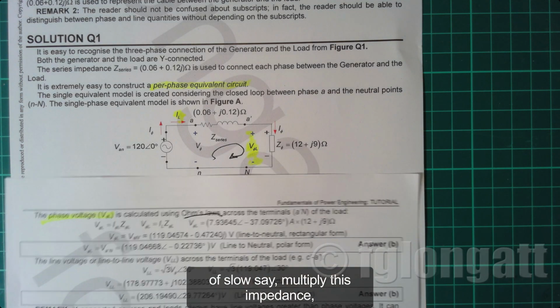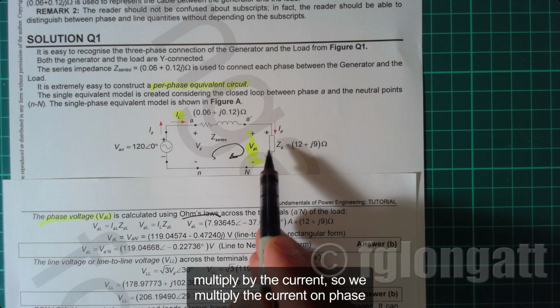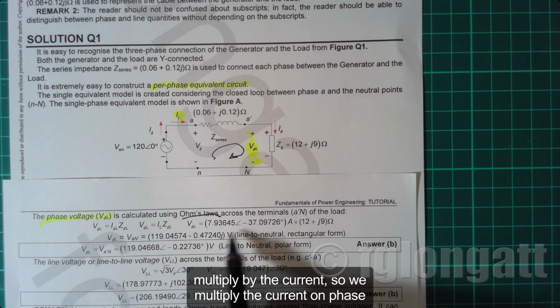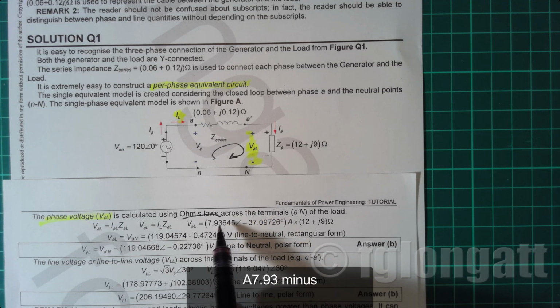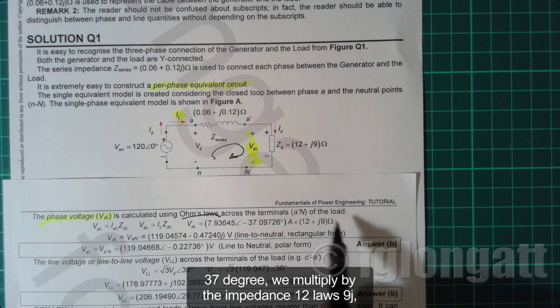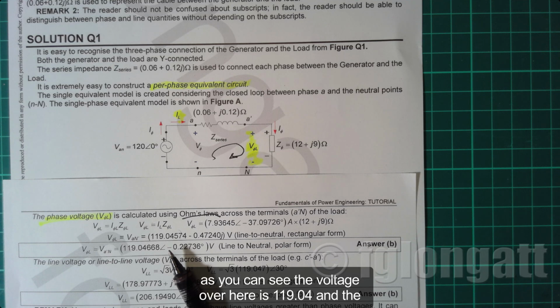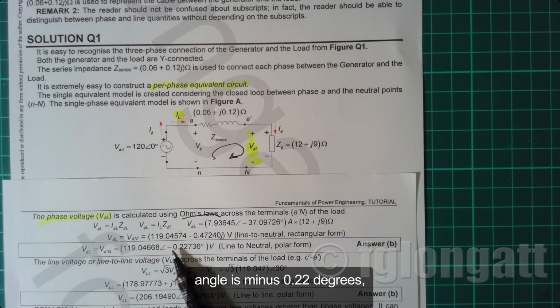and that voltage can be obtained using the classical Ohm's law. Ohm's law says, multiply this impedance by the current. So we multiply the current on phase A, 7.93 minus 37 degrees, by the impedance, 12 plus 9j ohms, and we obtain this beautiful voltage over here. As you can see, the voltage over here is 119.04, and the angle is minus 0.22 degrees.